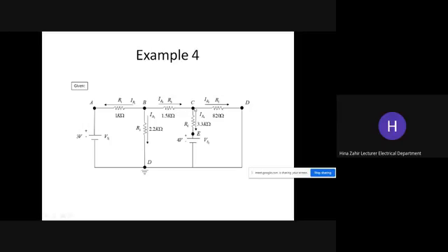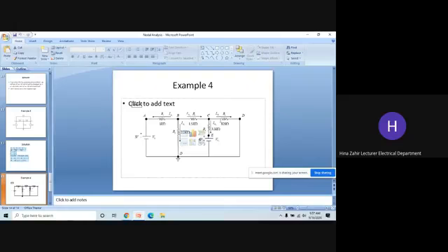Now let's look at V2. If I am going to write this current, V2 minus V1 divided by 1.5. What about here? Very easy. This is just like this branch. V2 minus 4 volt divided by 3.3. V2, what is here? This is 0. So V2 divided by 820. You do practice on different circuits and you would easily understand the concept behind it.